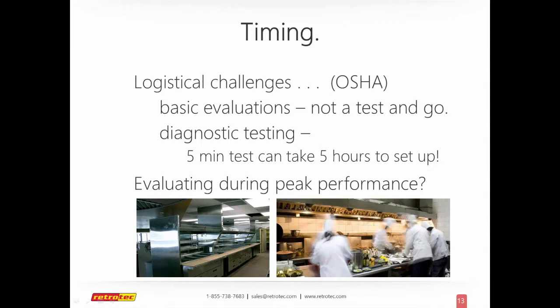One of the logistics in doing these types of evaluations is realizing that OSHA could be around, because these are commercial structures, and your basic evaluation is not a show up, pull out my door tester, or duct tester, blower door, test it and go, kind of do a walkthrough. The reality is you're probably going to be there for several hours without even pulling out any equipment yet. A diagnostic test could actually take 5 minutes to do the blower door, but it could take up to 5 hours to set it up depending on the structure.